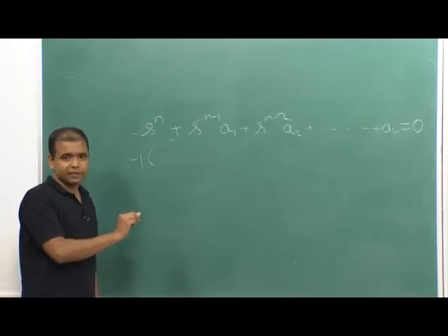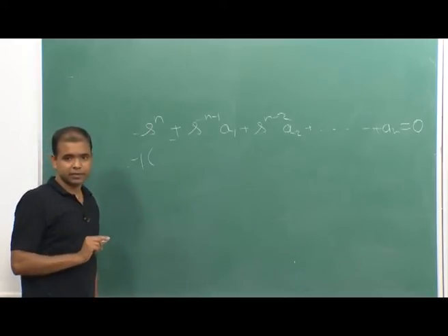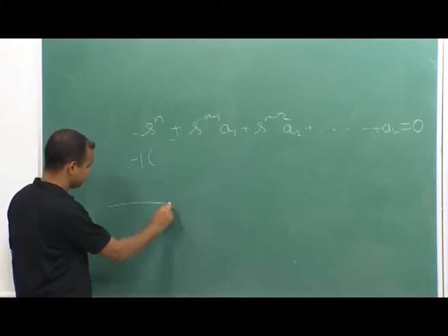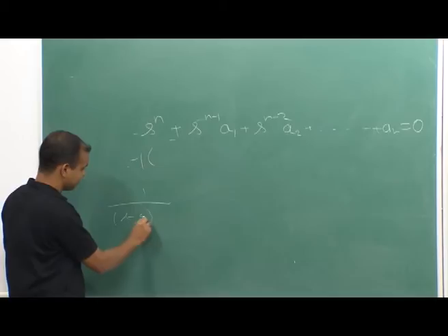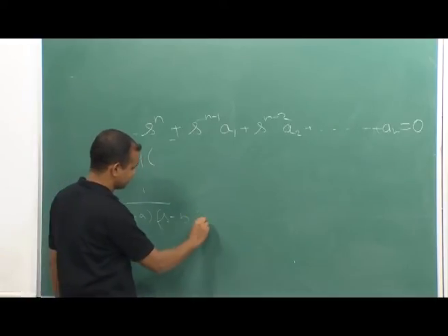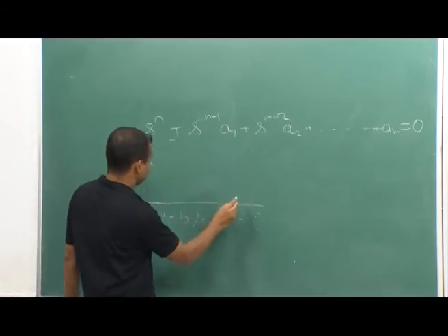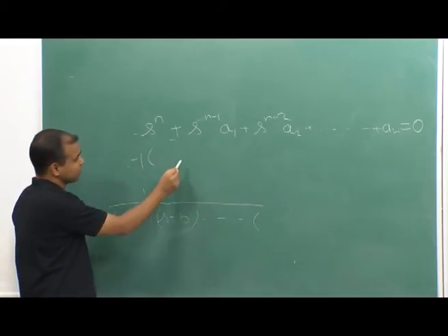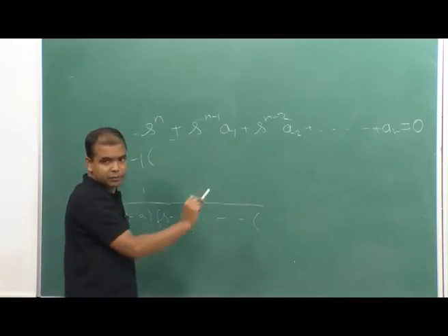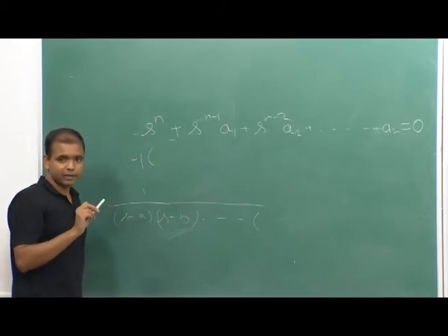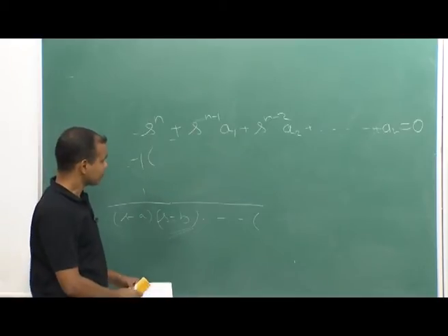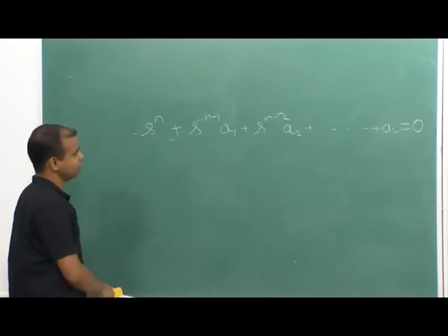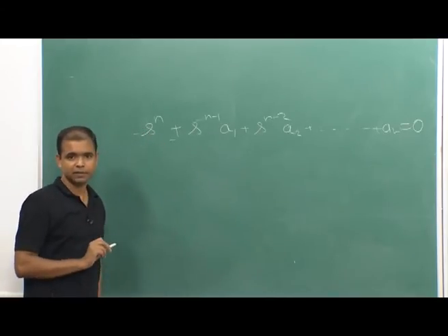If there is any sign change in the characteristic equation, the system will be unstable, and it is quite obvious, because if I have s minus a, s minus b or something like that, and there is any pole having a negative sign, it will reflect a negative sign in the characteristic equation. This means at least there is one pole in the right half. So, the first criterion of the Routh stability is that all coefficients of the characteristic equation must have a similar sign.